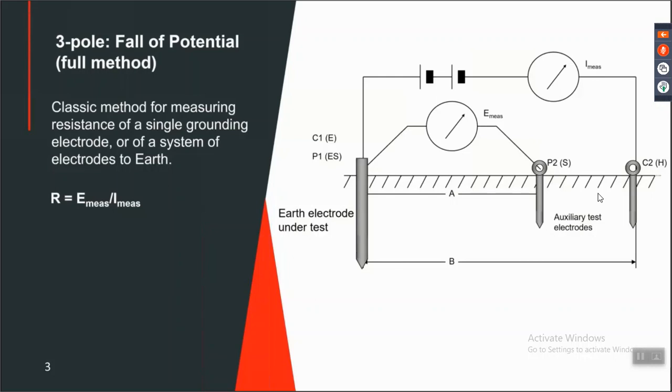The instrument will automatically step through its measurement range, and from the voltage it generates, the instrument calculates and displays the system resistance in the range 0.001 ohm to 20 kilo ohm, depending on the instrument tester.